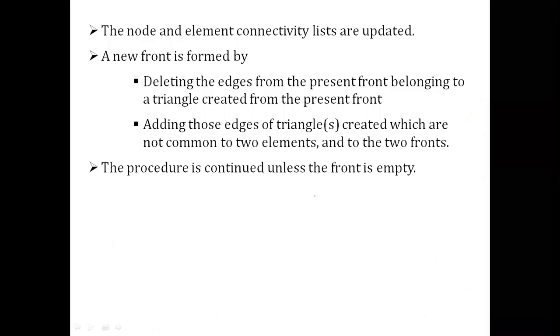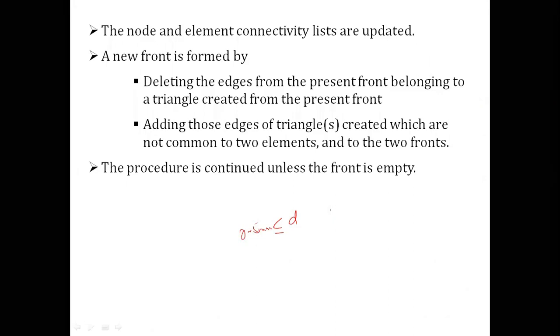So you define already when you put a node, that the node should be at a minimum distance of, say, 0.5 mm from each node. Once you put this condition and you see that the node cannot be further put, that means your triangulation is complete.